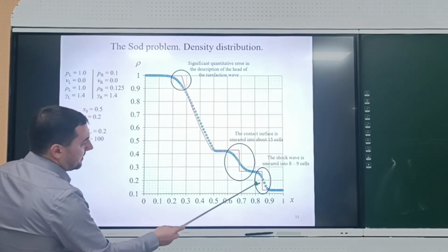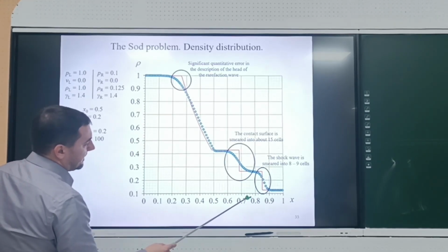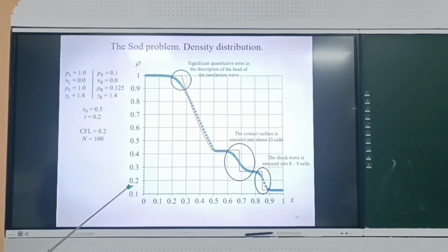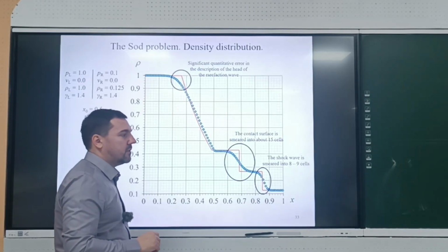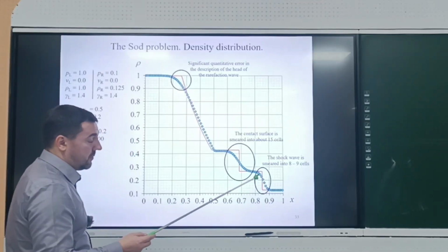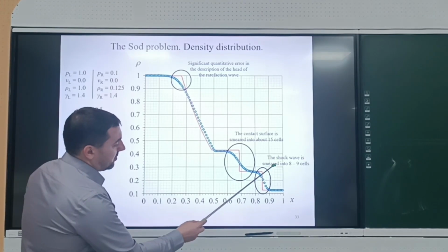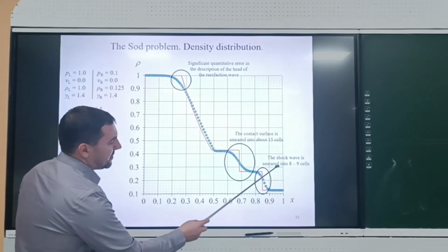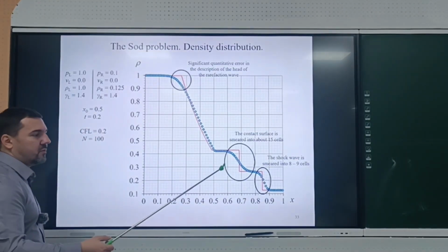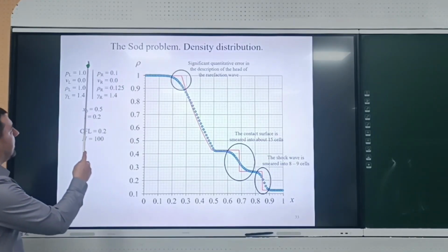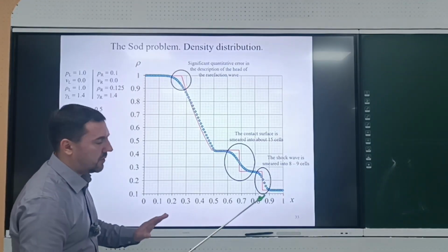So this is a shock wave. You can see that in simulation we have smearing of the shock wave, and the method that we use is a first order method. So we will have 2 lectures about the development of high order methods. But as for low order methods, first order method, we have the smearing into 8 or 9 computational cells, but actually this is not a constant. So this 8 or 9 depends on the problem. If you compute for a longer time, or if you change the parameters of the Riemann problem, we can get totally another number of smearing of your shock wave.